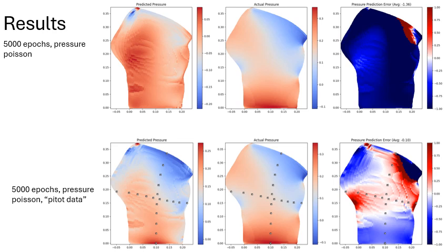On the top, just like before, the pressure field looks quite good now. It learned a lot faster, more or less, but there's still no reference pressure, so the values are quite far off. This is where the pitot probe idea comes in. What if we could give a neural net a peek at what the actual answer is? So we're going to put a pitot probe or like a pressure probe in the flow field and give it some of those values. So I said, okay, we'll do it down the middle.